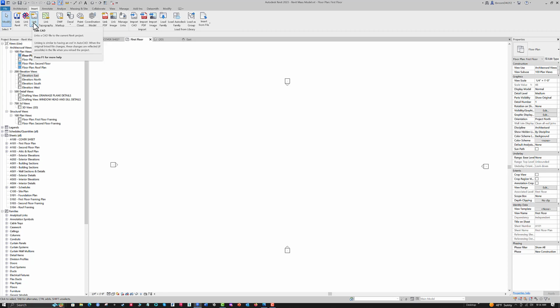Also, if I do that, then I can create a three-dimensional topographic surface from the engineer's drawing, as long as he's created a three-dimensional site plan. I don't really need to worry about that right now, though, maybe later. But what I do want to do is import a CAD plan. This just puts it in my drawing as a dead drawing, really, a reference. So I'm going to click on Import CAD.